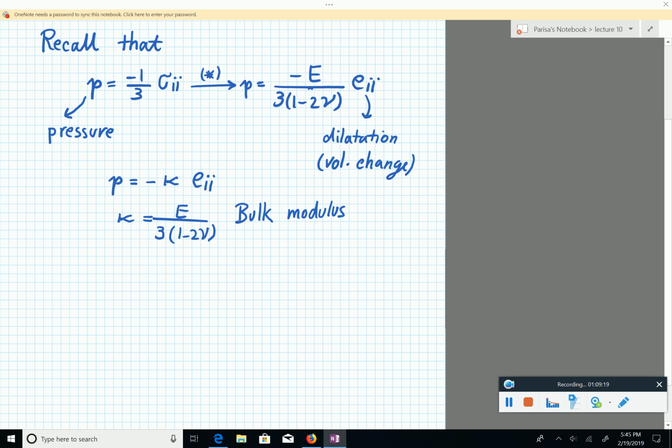No. Exactly. So the condition that you have to put there is everything that you have seen here, the linear elasticity. This is not true for all sorts of material models. Everything we are doing has all these assumptions built into it. Small deformations is the main thing, and linear elasticity. I told you we cannot have residual stress, we can't have rate dependency.